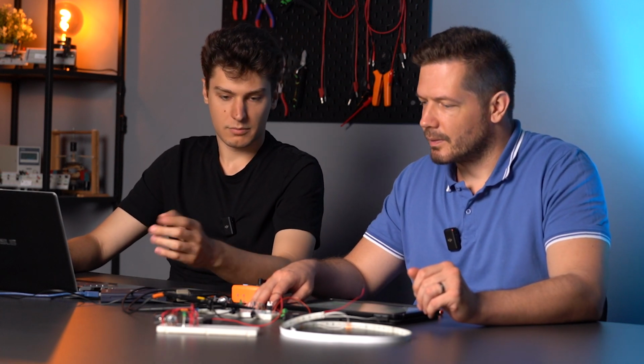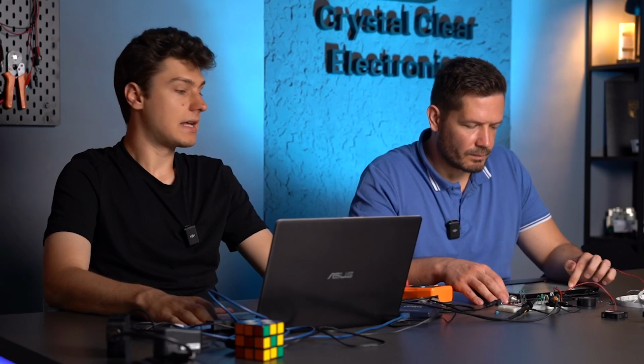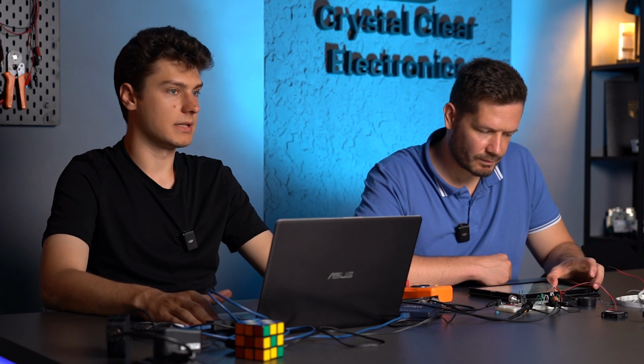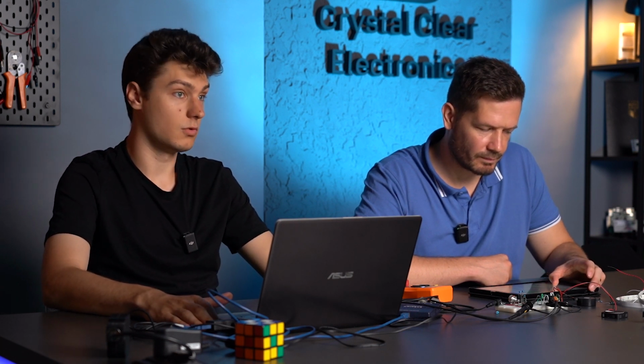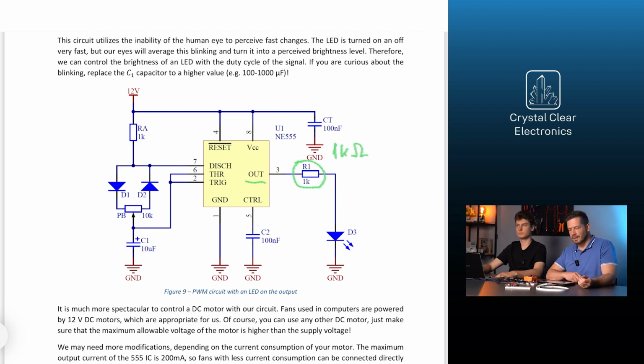Let's keep experimenting, always thinking everything through to avoid problems. Previous discussions have covered LEDs, and we will revisit this topic shortly. The LED ballast resistor serves as the resistor in this application. Its purpose is to establish the maximum current of the LED, which should be 10 mA for now. To achieve this, resistor R1 should be replaced with a 1 kΩ resistor. This is a familiar connection. And let's explain how the 1 kΩ was calculated.